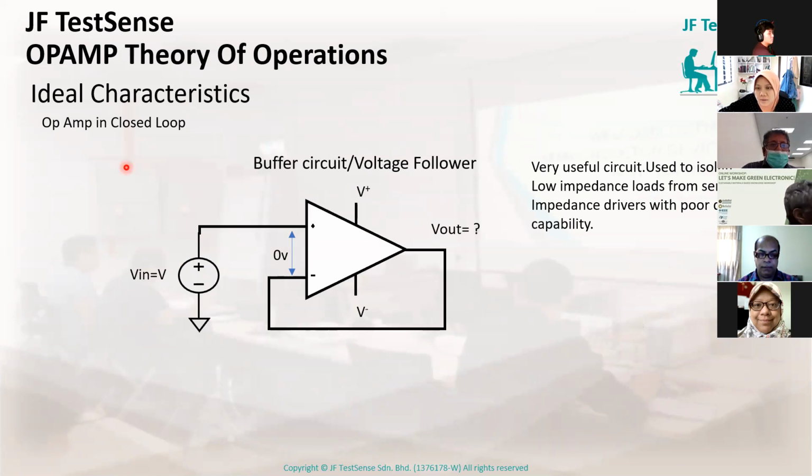So a very simple application of the op-amp we have is the follower. And in test engineering, this is a very common circuit that we use in order to isolate the impedance of our device from the tester resource. Because the device pin, which probably has high resistance, will see an infinite resistance, no current taken, right?